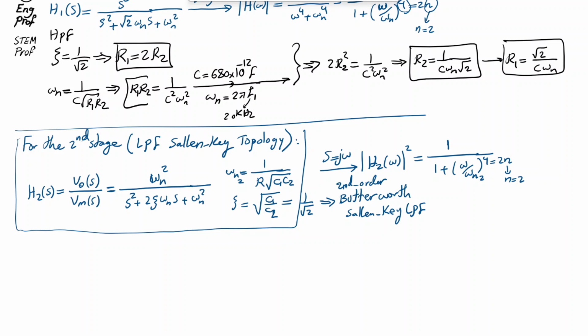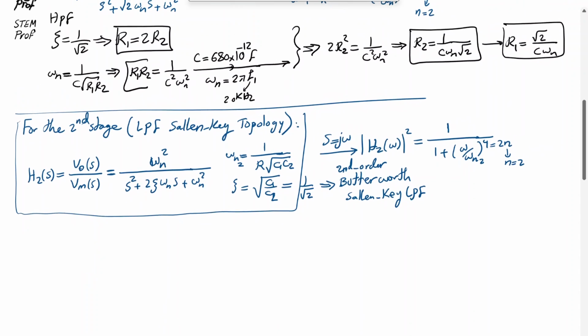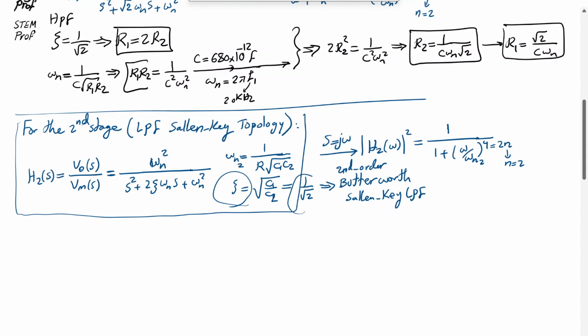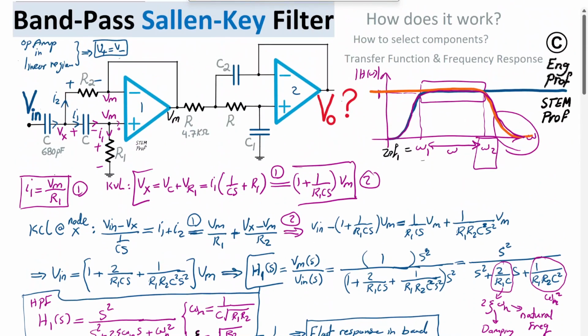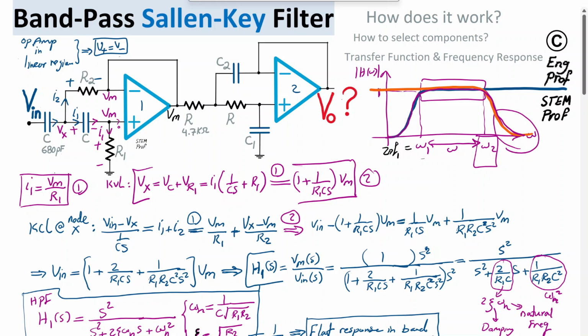Okay, so same idea. With setting zeta to slightly underdamped, 1 over square root of 2, and by selecting omega n2, which is exactly the target value for the second 3 dB drop. So remember, these frequencies are 3 dB points. We have a 3 dB drop at these frequencies, so effectively they define the bandwidth.